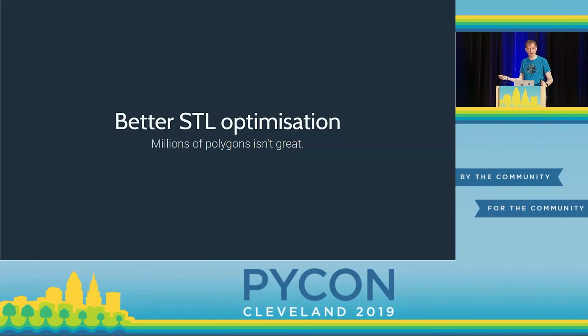And the other thing here too is better optimization. So I showed you the grid of how those polygons look. Well, it makes 2 polygons for every single grid point. Even if it's a totally flat lake surface, it just makes like 400 polygons on that surface. And so the result is a file with between 5 million and 20 million polygons. Now try and load that into a 3D modeling program. It will complain but do it eventually. Try loading that into a CAD/CAM program that's used to nice rectangles, it just quits. Fusion 360 just went nope and quit every time I tried to open it.